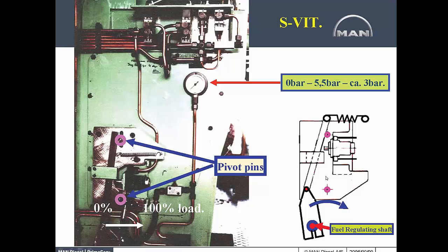The top will start to move left because you're pivoting off the lower, and then what that does is the bar moves away from the pneumatic regulator, and your air pressure then will change back. And this is how you would adjust this, and this is how they are mechanically controlling this variable injection timing off the governor.